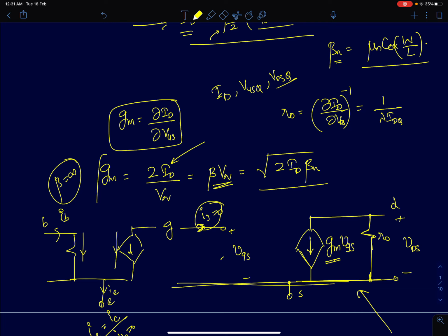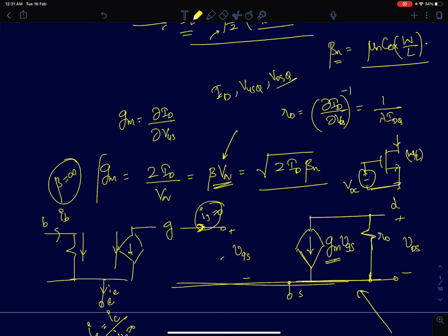We also said how gm changes by changing the drain current or the overdrive voltage. For example, if I apply a fixed DC voltage source between gate and source, so Vov is fixed, and I just keep increasing W/L, then one can intuitively see from the second equation that as you increase W/L, your drain current increases as well, so your transconductance will actually double.